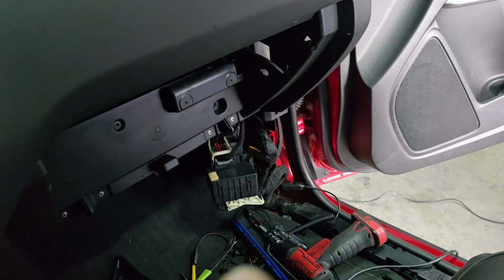There was a fuse that keeps blowing, fuse number 18 in the passenger side fuse box, on the inside, right there in the right side kick panel. That fuse, as I'm showing you here in this diagram, feeds two things: the restraint control module and the passenger occupant restraint module, a little module located under the passenger seat.